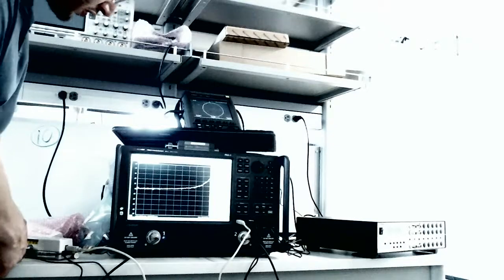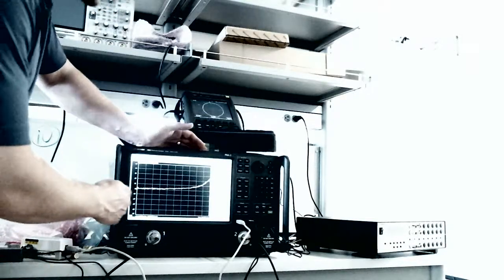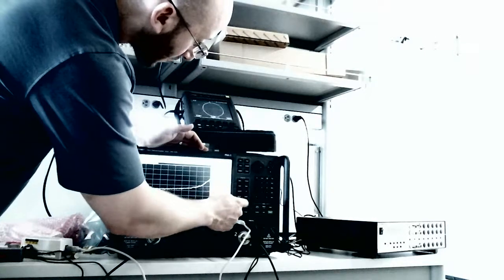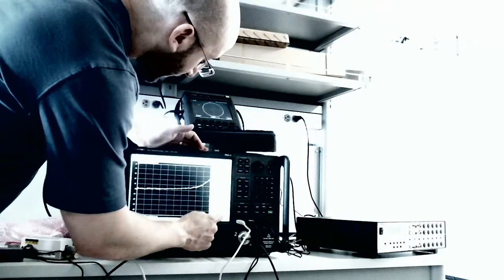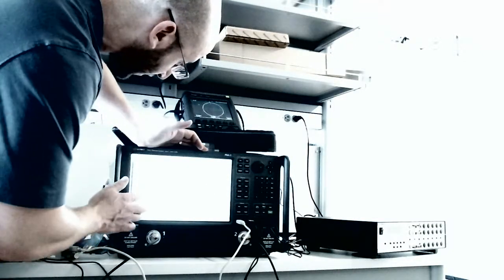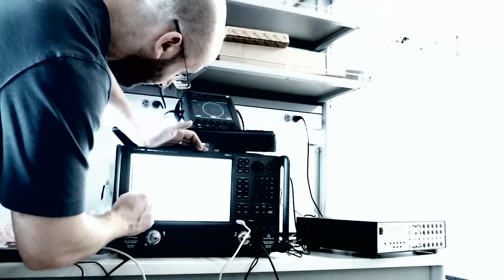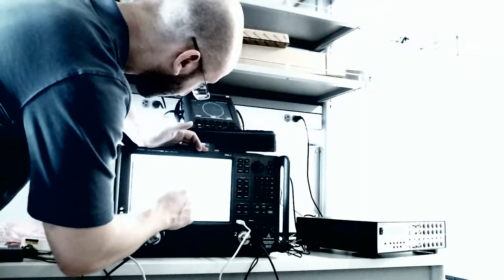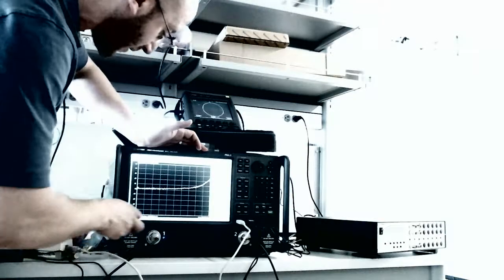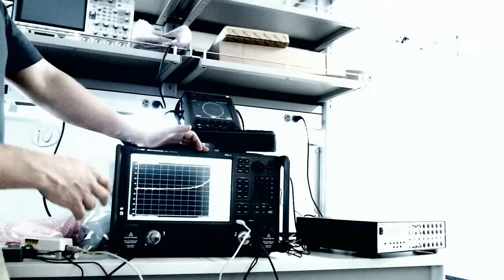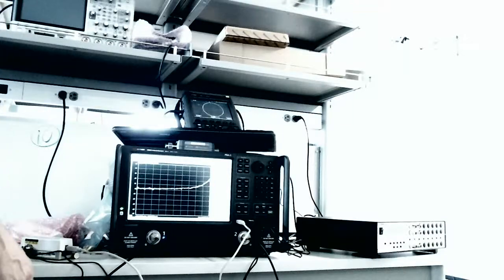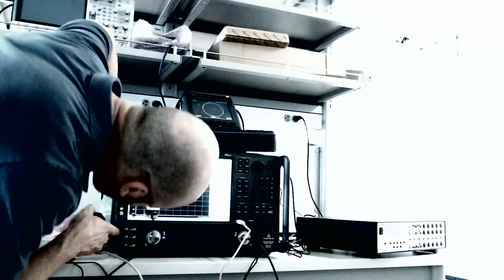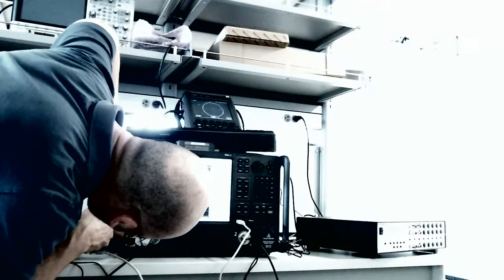So what you do with that now is, if we go back and go under this to noise figure setup and go to noise figure now, we should have access to the tuner. Maybe it just takes a little while to correct it. And I need to connect this in series. There's a setup diagram on how to connect this with this. It actually tells you as well. It says here's where you would connect the noise source.